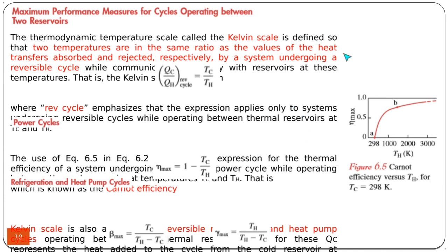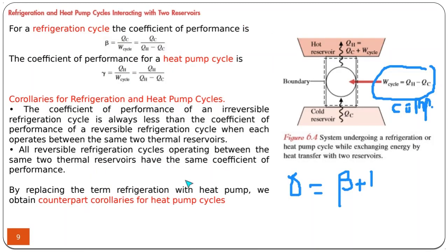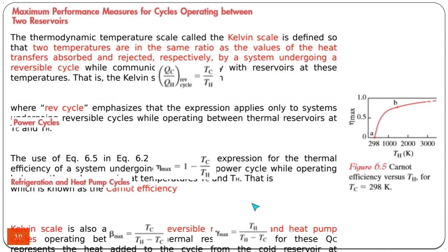When this system converts the PowerPoint slides, some distortion occurs, but in any case, you can see them. In the case of Carnot heat engines and Carnot refrigerators, instead of using the ratio of the heats, you can use the ratio of the temperatures. So for a Carnot system, for a reversible system, the ratio of the heat can be written as the ratio of the temperatures. So you can see that it's a reversible cycle, meaning that it's Carnot.